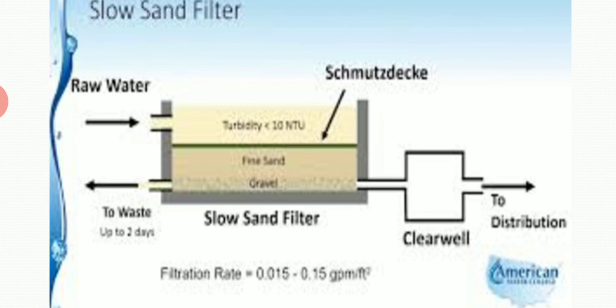The impurity which is settling is marked with a green color line. This process of impurity getting arrested above fine sand, which has a lesser pore size, works like this: if the impurity is greater than the pore size, it gets arrested on the fine sand. This process is called mechanical straining.